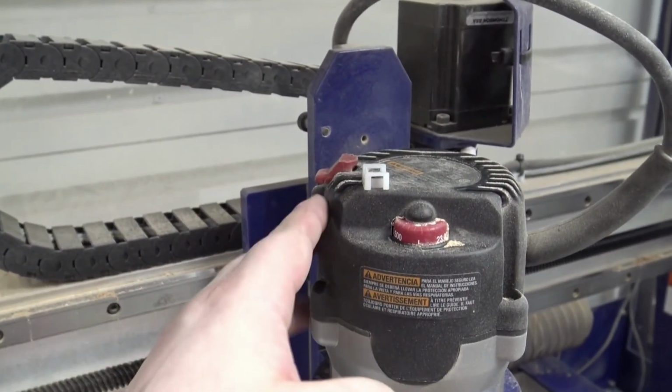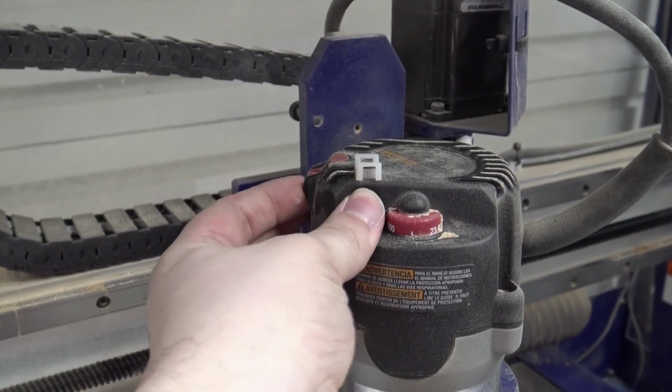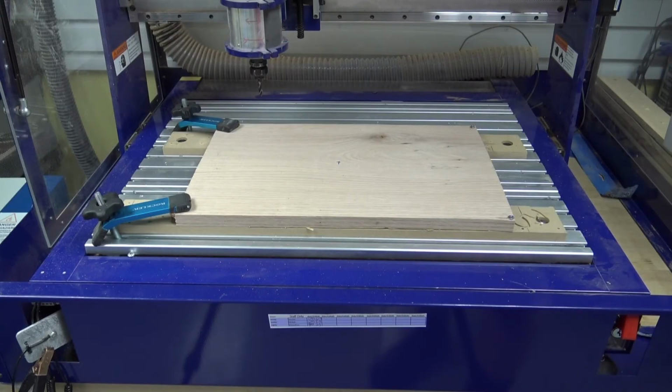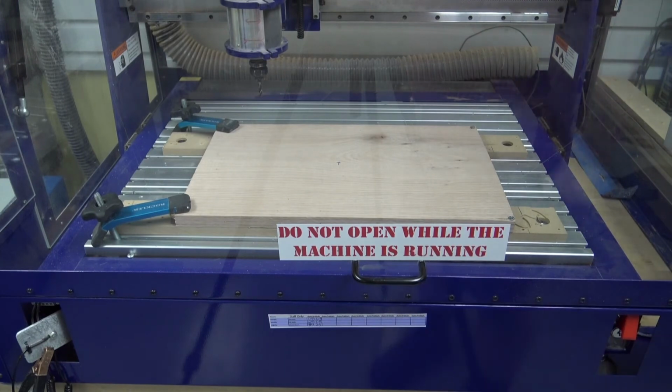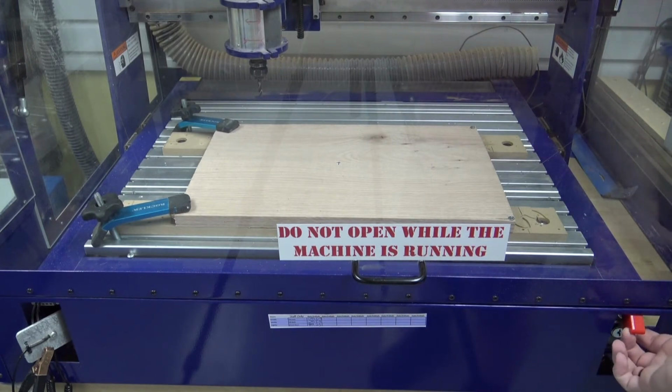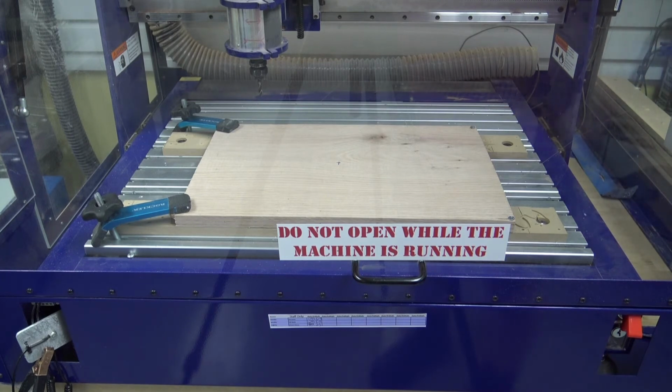Now is a good time to verify that the spindle safety lock is in the up position. As the machine will start moving now, it is important to close the lid on the machine. Next, turn the machine on by flipping up the red switch and then flipping the toggle switch underneath of it. This red switch will act as the emergency shutoff button in the event of an emergency.